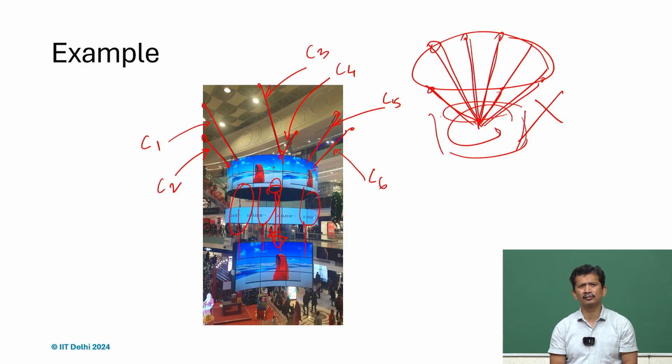Of course, that has to be analyzed, and you may realize that the lower one is basically not constrained, because 3 cables will only provide 3 constraints, but the top one is definitely constrained with sufficient force, and you have 6 constraints, 6 cables. So, it will provide all the constraints. Very nice example, and one can always think about it.